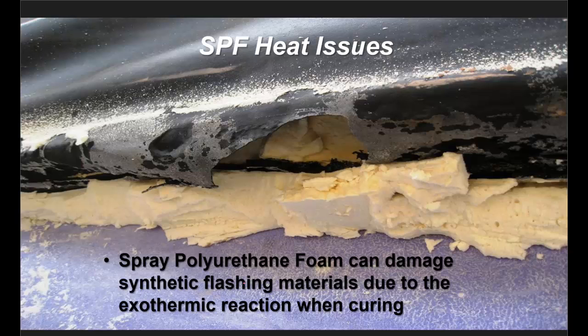If you have spray foam and you're using it in your cavity as continuous insulation, make sure that the flashing you're using is able to withstand the heat from the spray foam when it cures. When it cures, it creates an exothermic reaction. It gets up to 300 degrees. Well, if that's hitting a plastic or an asphalt or a rubber, you can guess what happens there. And what happens is exactly in the middle here, a hole that has been melted, burned into the flashing.